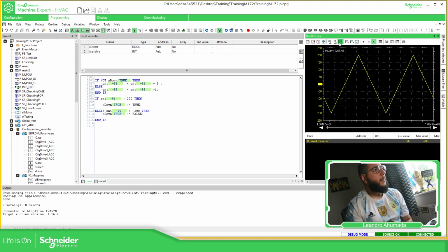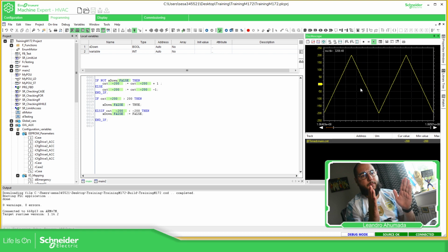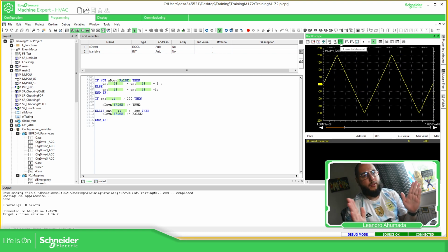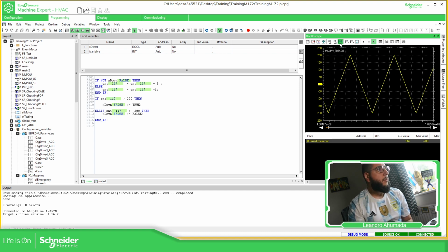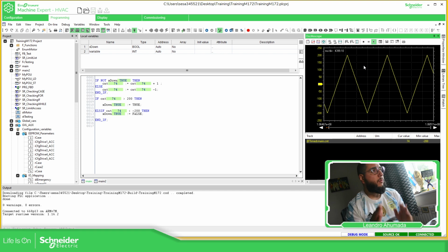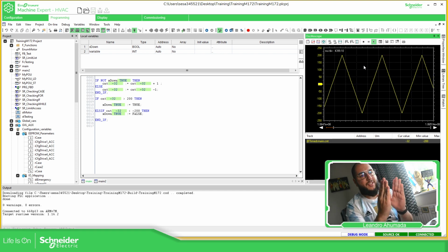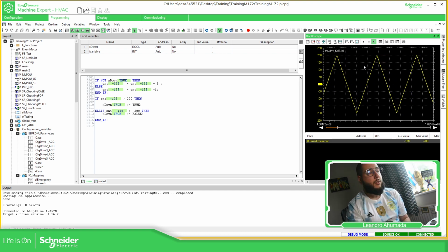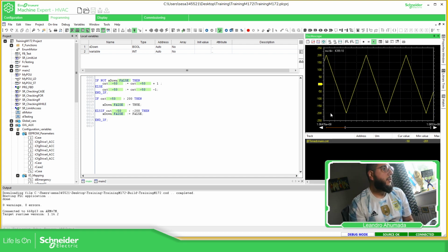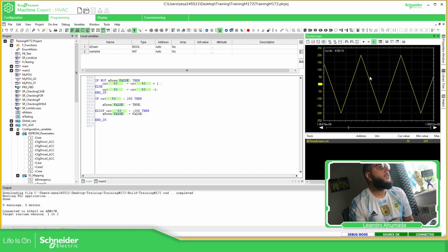We can also expand and see the data in a much better way using this to expand all the horizontal to show all the data. If I press again, it will use from the beginning to the latest one. And you can see how the period appears to decrease, but it's the same period, it's just the time per division that changes.